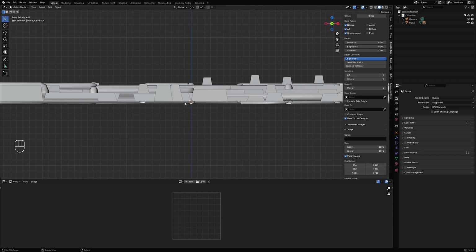Okay, so origin points, we're just going to use the origin point. Lowest geometry, if there is something extruding far beyond the origin point, we're going to use lowest geometry. And selected vertices, if you had something like extruded geometry here and you've selected these faces, you can manually select these faces, and this area will be used as the 0 point for the displacement, if you have selected the option for the depth location, the selected vertices. But since we don't have any of those exotic geometries protruding under the origin point, we're just going to use the default origin point option.